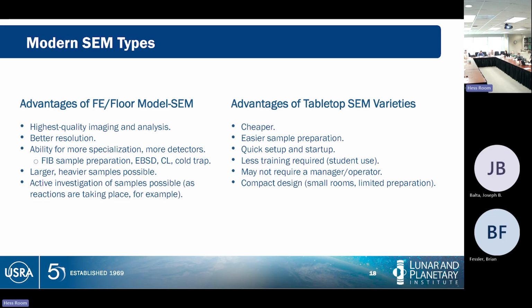The desktop or tabletop SEM varieties are much cheaper. This makes them far more accessible than the full lab scale facilities. You can have multiple ones of these on a single university and give everybody access to them. Sample preparation is often easier. You don't have to worry as much about everything holding together in there. The startup and setup are quick. Training required can be quite limited. We can put an undergrad on ours in a few minutes if we need to.